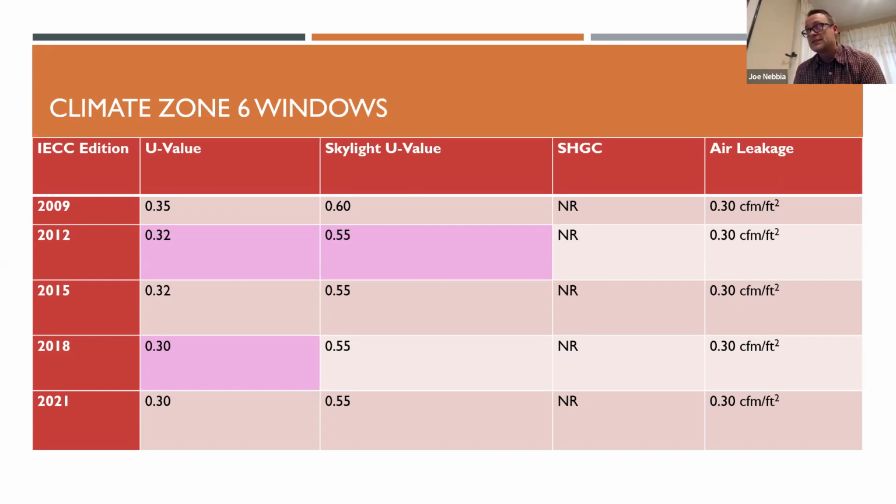It's not always tested, so it's important to make sure that's on the label in your window because the test itself isn't mandatory, but any code in an IECC, International Energy Conservation Code, jurisdiction should have this test done because it's been a requirement for quite some time, since 2009. So make sure that the home does have that air leakage number on there.